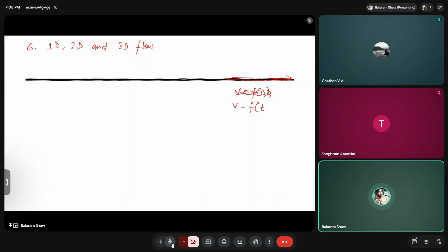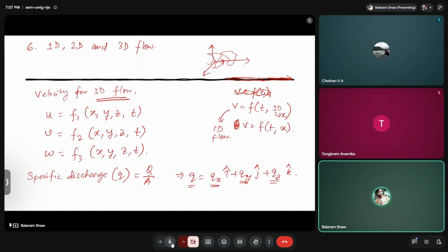If the formation is homogeneous and isotropic, we know what is homogeneous and isotropic, right? And the groundwater flow is incompressible and inviscid, so we are considering one ideal flow. In ideal flow, we'll have the layer as homogeneous and isotropic, the flow incompressible, inviscid, and so on. The components of this specific discharge will be given using Darcy's law.